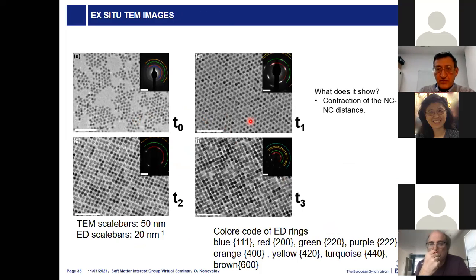What we see is that over time the lattice parameters change, because it becomes constrained. At the beginning we have, for example, very rare random patches. Then it creates a hexagonal structure. Then it changes to something closer to cubic, and then here it is cubic. Also we see in the TEM diffraction that there are different Bragg peaks, Bragg reflections, from the system.